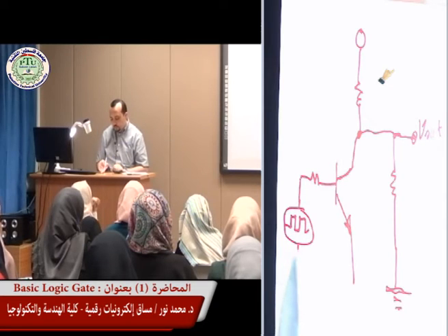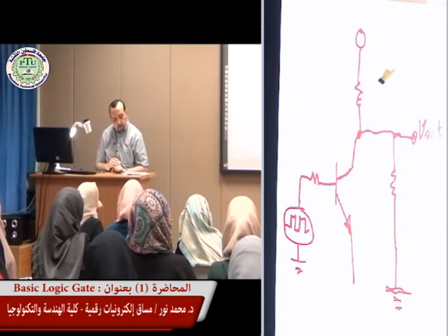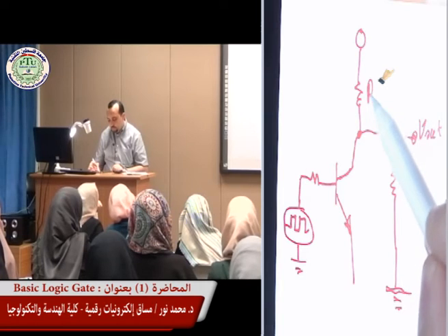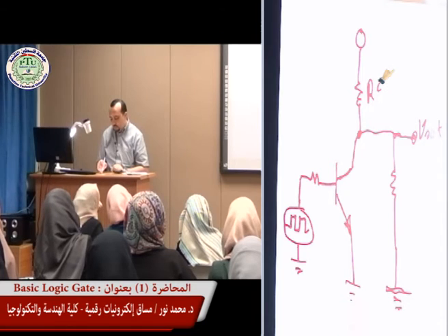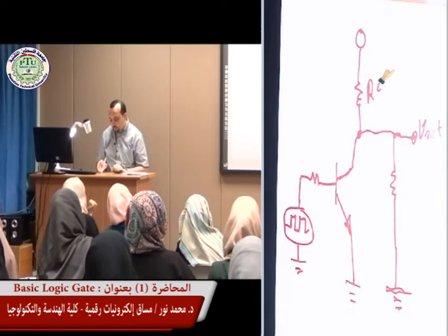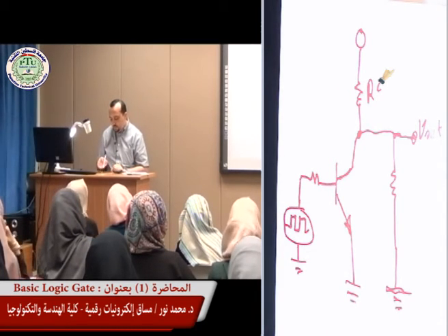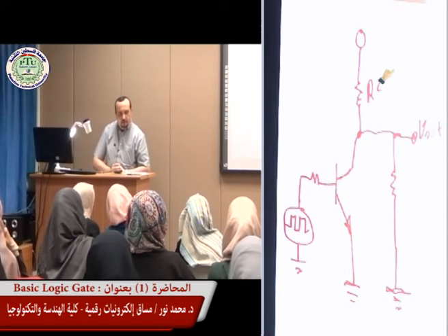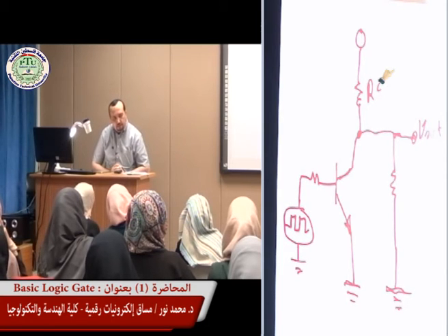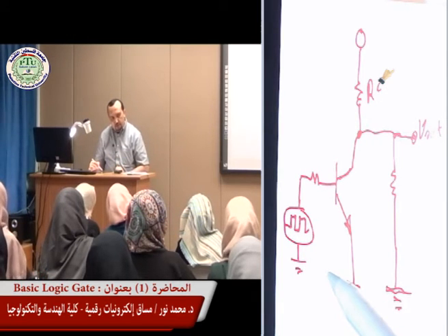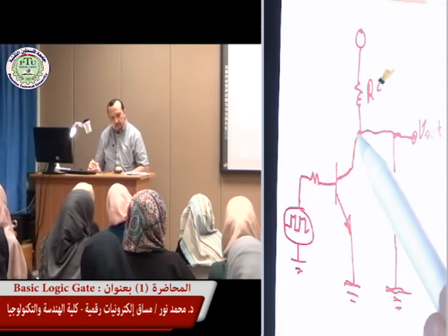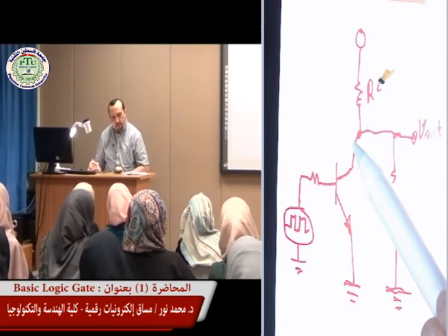Okay, so grounded. Now this is the RC, and here the emitter is basically connected to ground. Does anyone know what this type of circuit is called? I think the common. Yes, the emitter and the input signal are connected with the ground, so they call it common emitter, and the output is taken at the collector side.